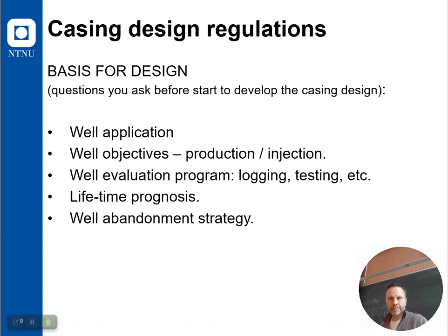Basis for well design. These are the questions that you need to ask before you start developing them, right? What is the well going to be used for? Is it a producer? What is it going to produce? Is it going to be a water alternating gas injector? Is it going to be converted to an injector later on? Blah blah blah. Is it going to be fracked? Blah blah blah. I mean, how long is it going to produce for? And what is going to be the abandonment?